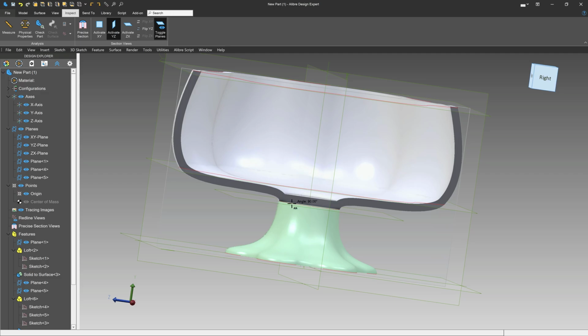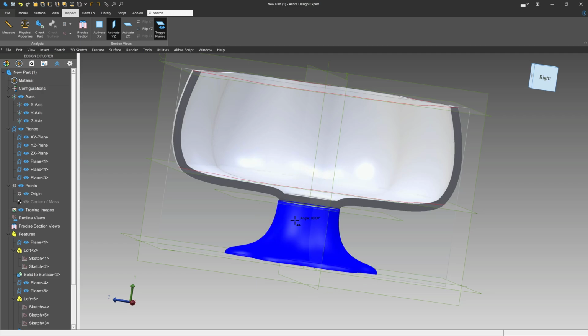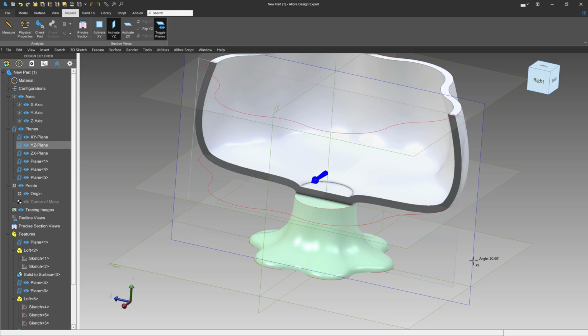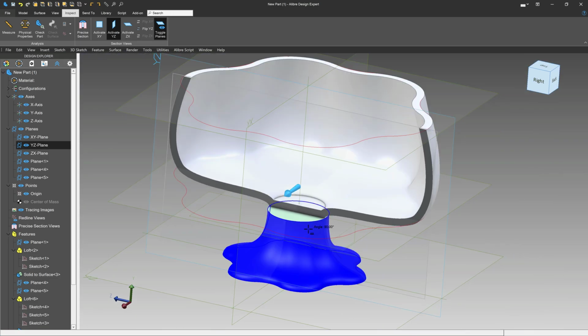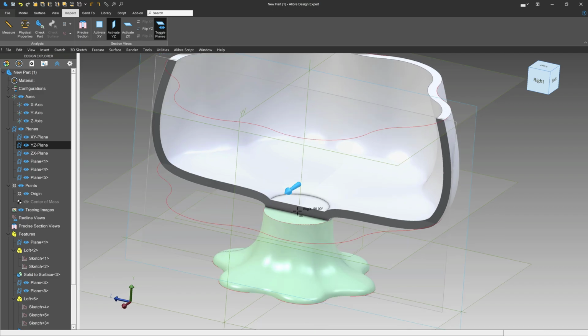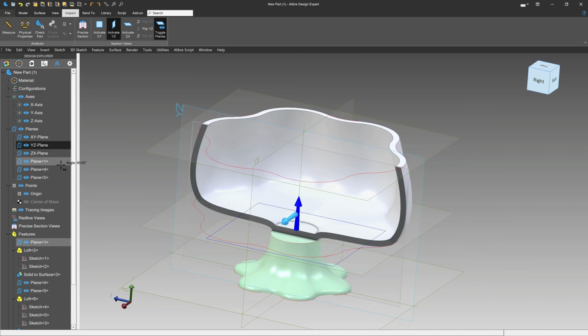You can run this as its own loft and then loft out the base, right? You don't have to do it in that kind of order. But if you have a workflow that's a little tricky, or you have to do it in a certain order, this can be a real lifesaver because it can help you control your shell. So that's one approach that you might be able to keep in your back pocket should you ever need.